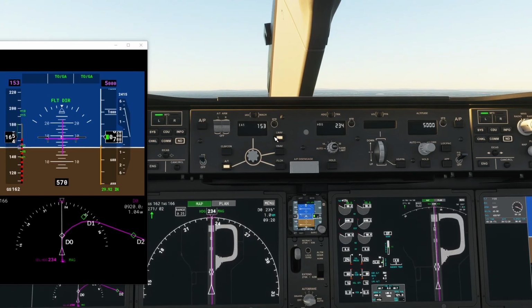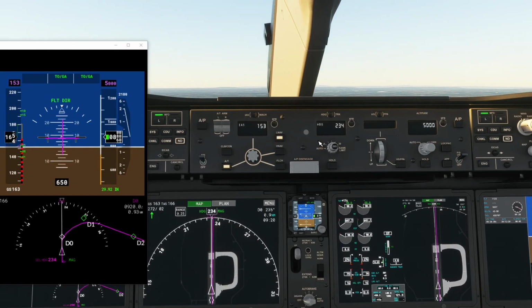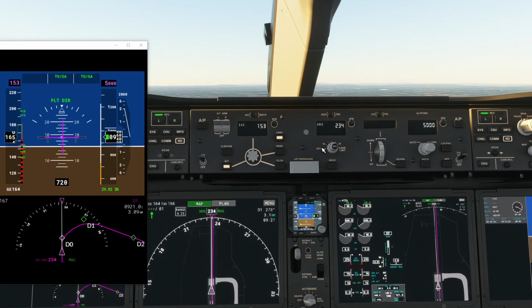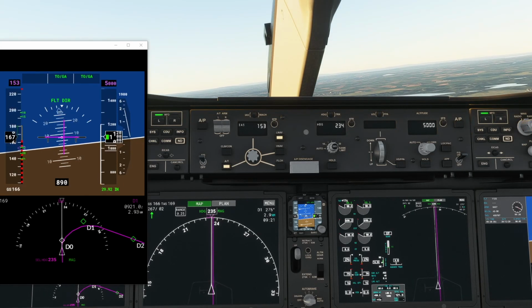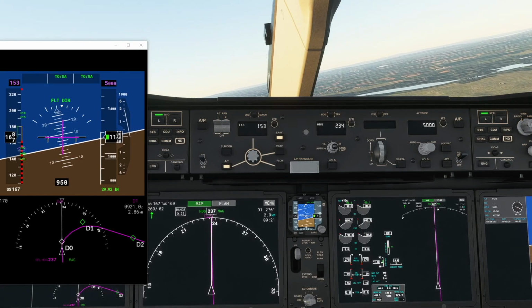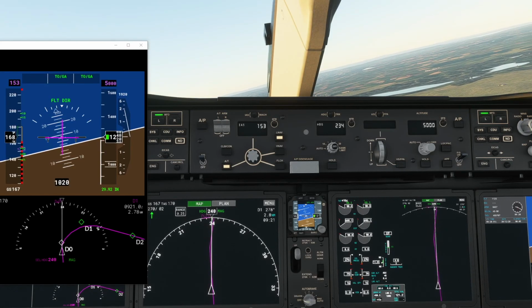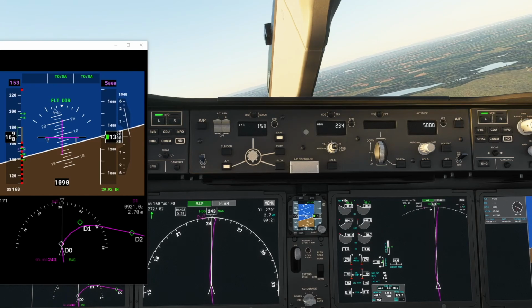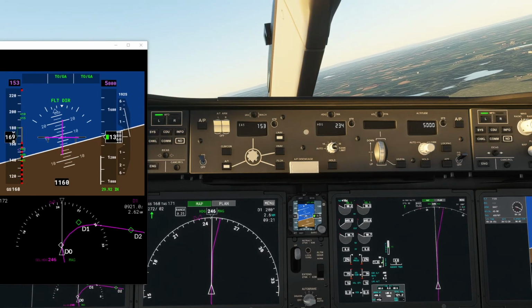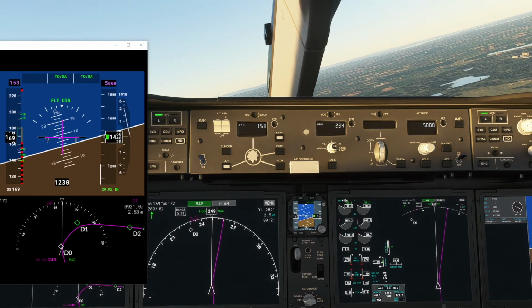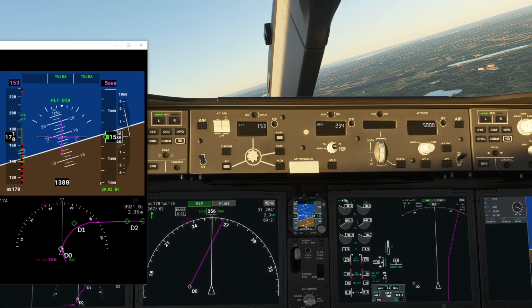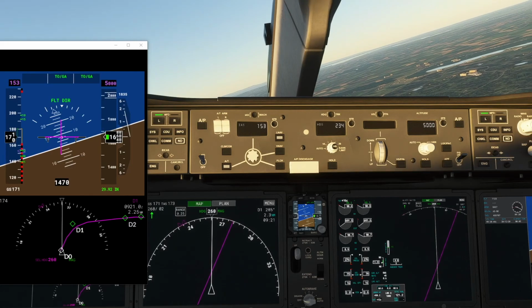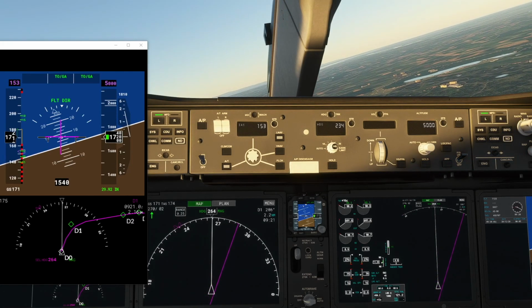We should normally rotate a little bit earlier than that, a little bit higher than that, to around 15 degrees. So the flight model in the flight simulator isn't quite there. It's had us rotating to just under 10 degrees, and I know from experience that's not quite enough. It's also got our speed rather low, close to the clacker at 170 knots. The clacker being the barber's pole there, which would warn us of a stall.